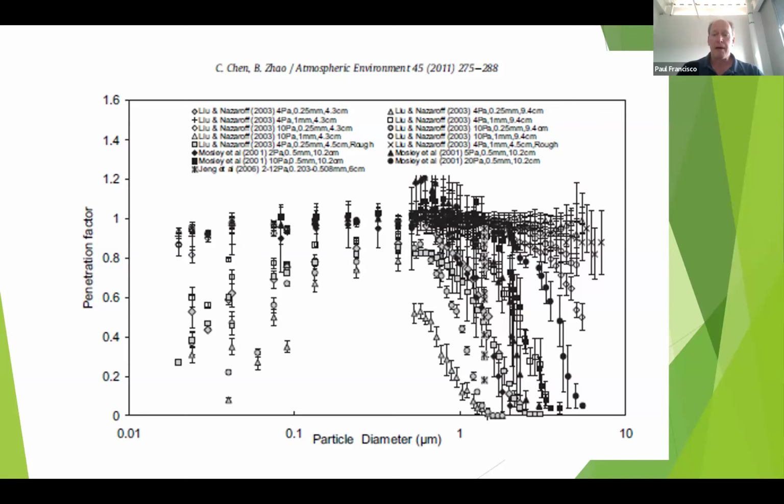And so if we think about, say, the middle of the winter, when it's not like it is now in the 60 degrees, but how it usually is, a lot colder, by having it colder, you have more infiltration because the stack pressures are larger, but you also are increasing the penetration factor as well. And so it's actually doing more than just bringing in more air. The fraction of particles within that air that are being brought in is going to be a good bit higher for some of these size ranges.